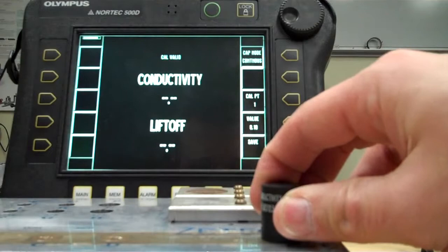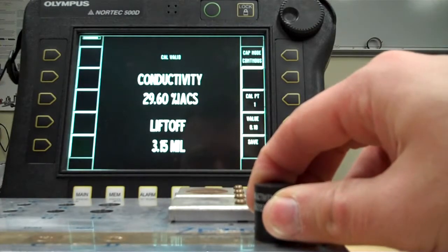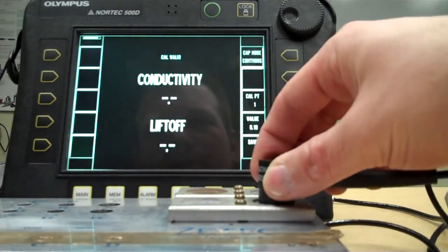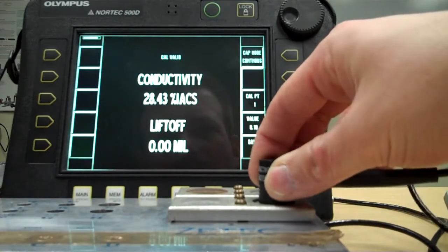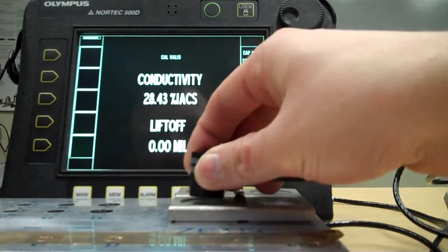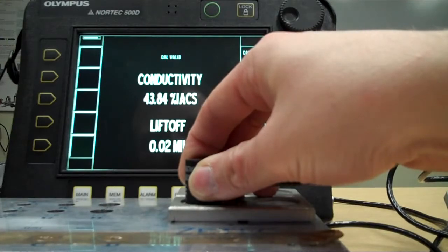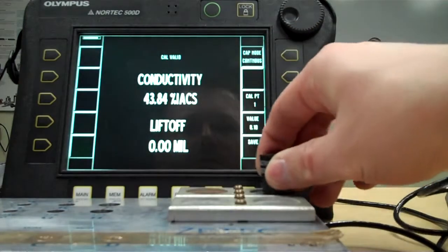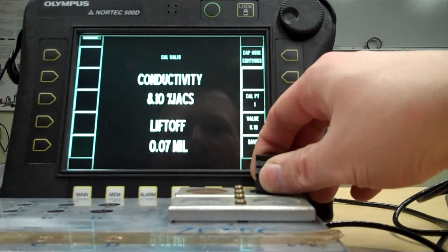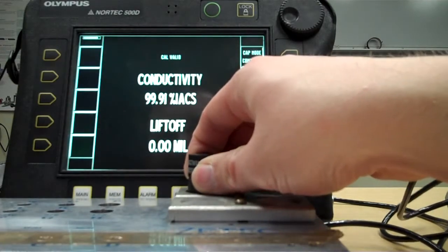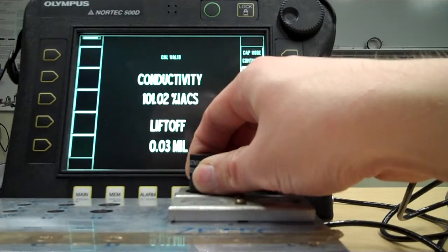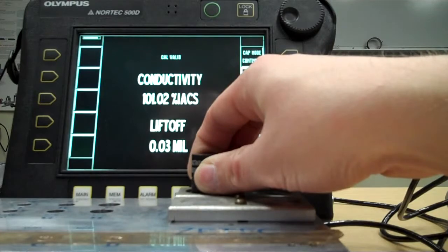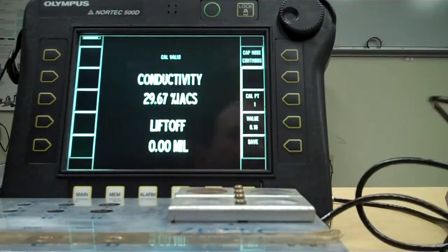So, just taking a look back at these same things. That's 8, that's lead. Let's go in the middle. This says 29.3. We're about 1% off. That's not horrible. About the same, this says about 45. We're about 1.5% off there. We calibrated to the lead, 8.1. We calibrated to the copper. There we are, 100.1. And it's a continuous thing, so it's always measuring as well.